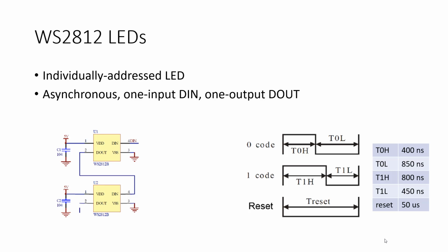Now, you might say, well, you have to put the number of cycles in for each one of the highs and lows? That seems wasteful. Well, that's just kind of a conceit of the peripheral. You have to explicitly put in the cycles for high and low for every bit, even though there's only 4 different options here.